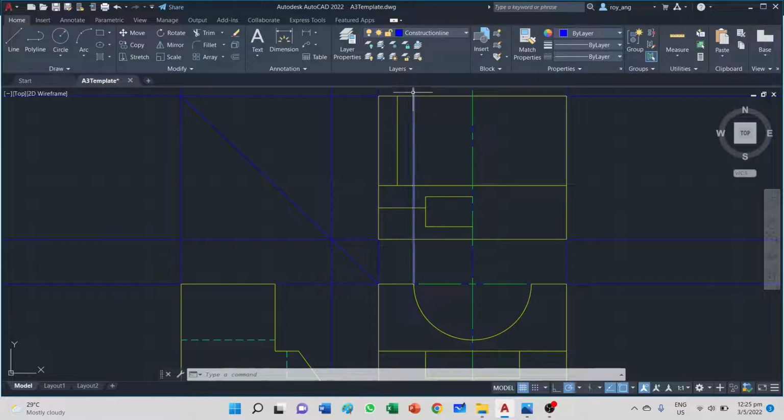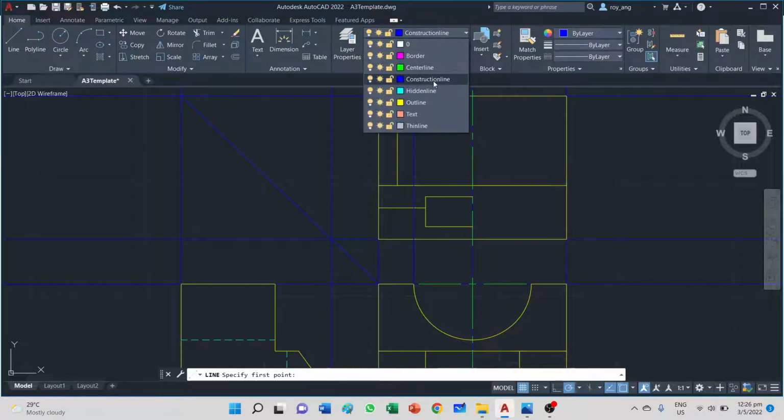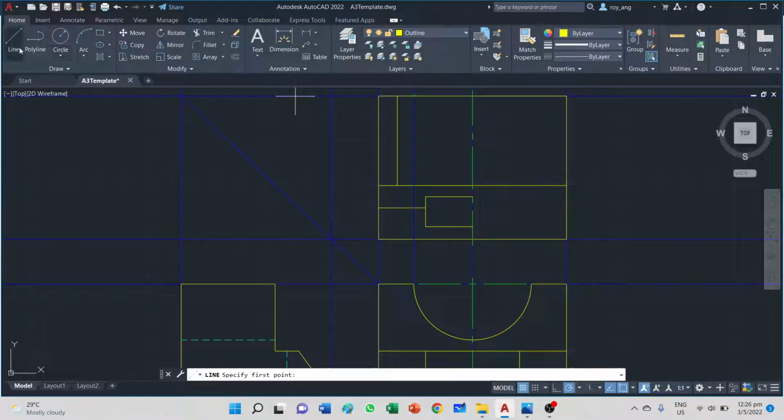The thickness of this comes down from 10 millimeters. So I'm going to use my outline and draw a line, and it's going to come down by 10 millimeters. Enter. And it's going to go in by 10 millimeters. Likewise it's the same from the bottom, it goes in by 10 millimeters, and then it touches this line. So I'm going to trim this away.